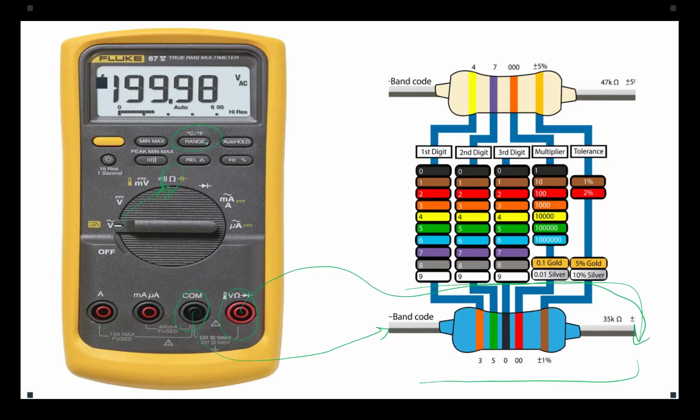Very good. Now, another fact, when you want to measure a resistor, there should be no active power source in your circuit. That also would affect your measurement. So everything is off, we are de-energized, and then we are going to measure that resistance. And if you want to measure a specific resistor within the circuit, you need to disconnect it, because otherwise you are going to see the equivalent resistance of that pair. Does that make sense? So remember those things.